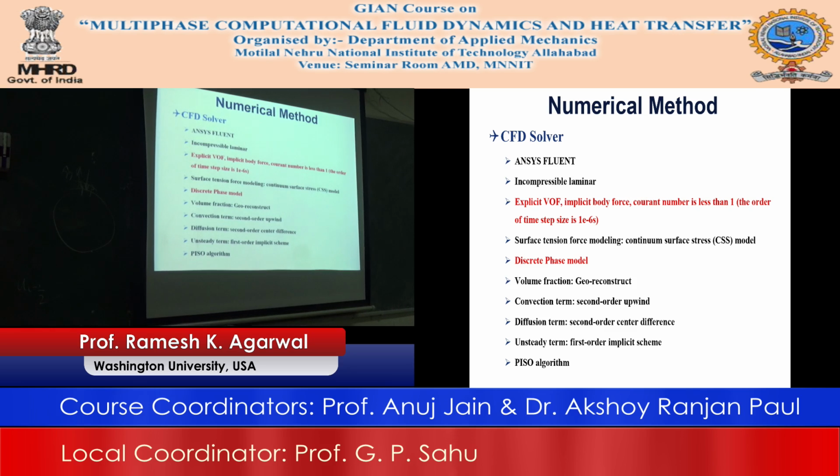What may happen is, the point here is that surface tension modeling, at least what my students have found, is that... now we are going to use the discrete phase model for this particular case. You could use some other model. And then volume fraction, which means VOF, with second order upwind, second order central differencing, and implicit scheme, and instead of SIMPLE, we can use PISO, which is like a SIMPLE algorithm.